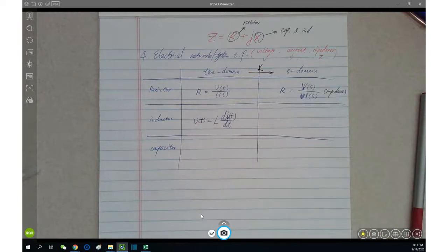The voltage of the inductor might reverse direction. However, the current won't. The voltage might bounce between positive and negative, that's possible. However, your current won't, because as you know, the current through the inductor cannot change instantaneously, let alone change polarity easily.